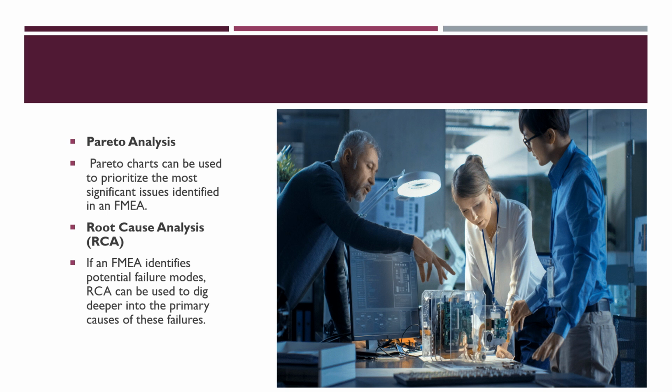Pareto analysis. Pareto analysis or Pareto charts can be used to prioritize the most significant issues identified in a failure mode and effects analysis. It visually depicts which failure modes have the highest occurrence, severity, or detection scores, and therefore require immediate attention.